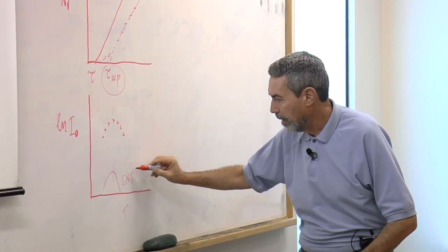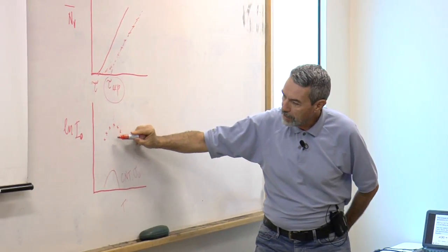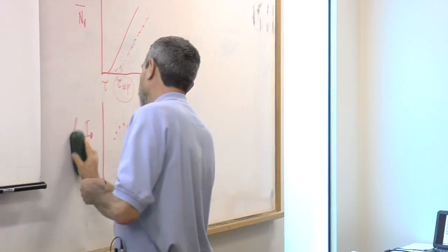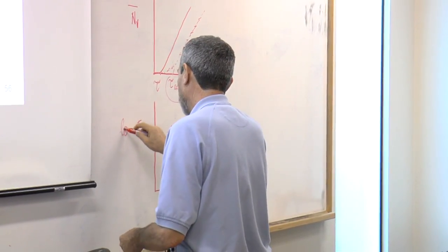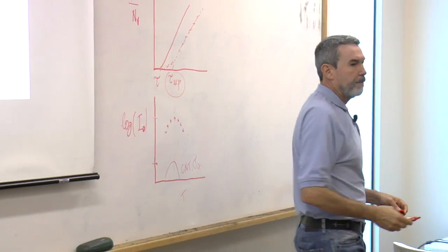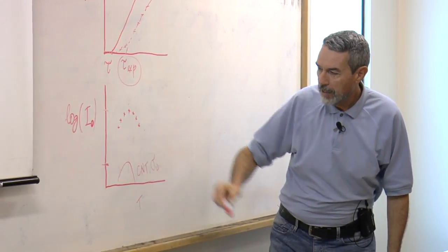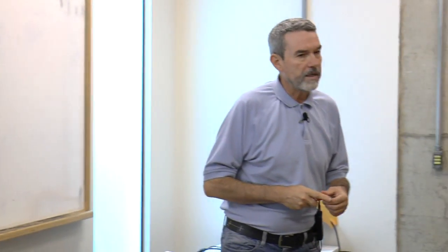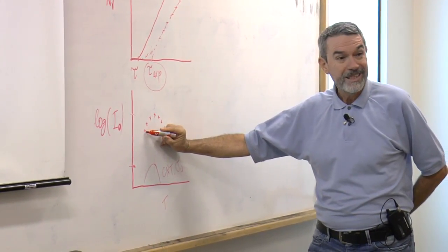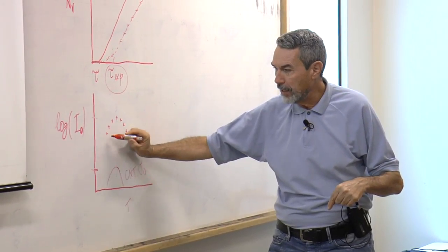classical nucleation theory, with a constant value of sigma, you remember these huge discrepancies of many orders of magnitude. This is log. Let me put here in logarithm scale. So there is a huge discrepancy, 20, 30 orders of magnitude discrepancy. Now you can do another exercise. You can take this data point here and calculate what's the surface energy to bring agreement between the theory and the experiment.